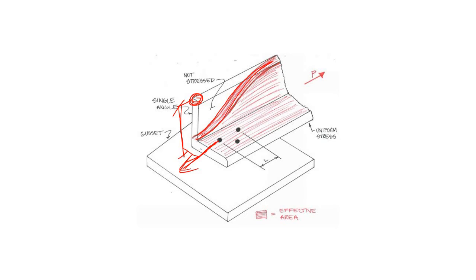So if we simply compare this with a weld connection, in this bolt connection, this is the point of load application and this is the farthest point which is not stressed. But in case of a weld connection, this is welded, this is welded, and that side also welded. So from this farthest point which is not stressed to this point of load application, this width has been reduced, so this stress development will occur much faster compared to your bolt connection.